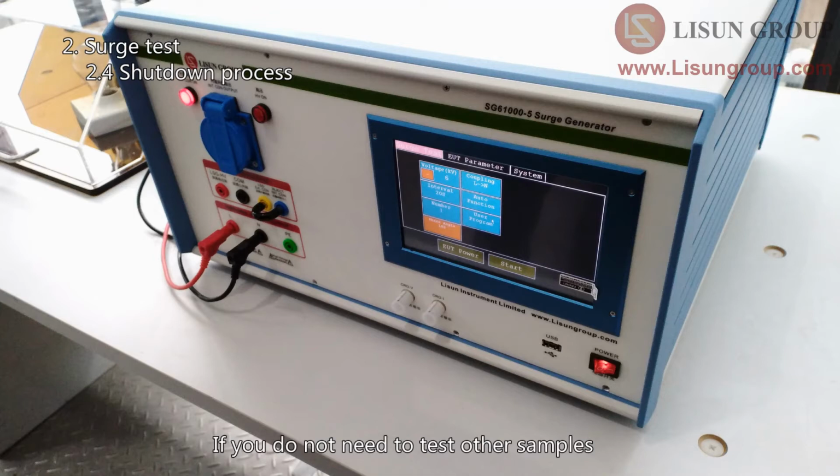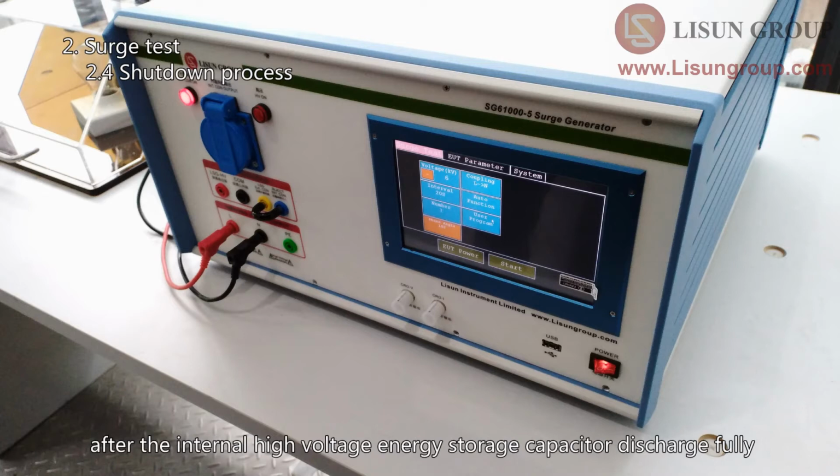If you do not need to test other samples, confirm that the touchscreen surge test is in the off state. Wait at least 5 minutes. Turn off the surge generator after the internal high voltage energy storage capacitor discharges fully.